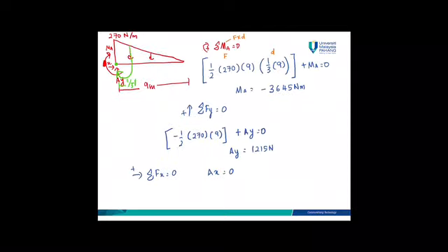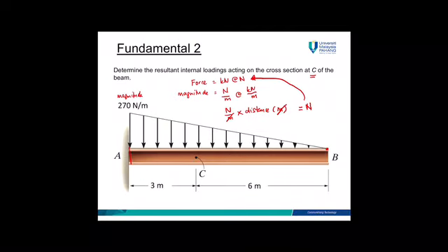Now we will calculate the internal forces at C. First, you have to draw the free body diagrams. Choose the simplest shape. This is your C. You can start from A or you can start from B. It depends which one is the easiest one.